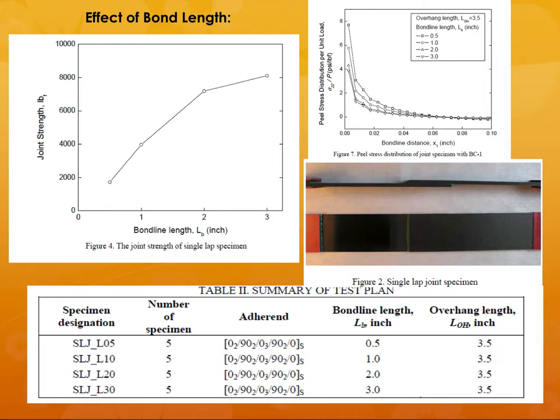And the other thing is that you have to make sure that the bond length is right. If you have an entire surface to be bonded, like if this whole surface has to be bonded, you don't put it at every couple of points. You probably apply it through the entire joint, so that when you test it, it is going to withstand the temperature, pressure, and stresses, etc.